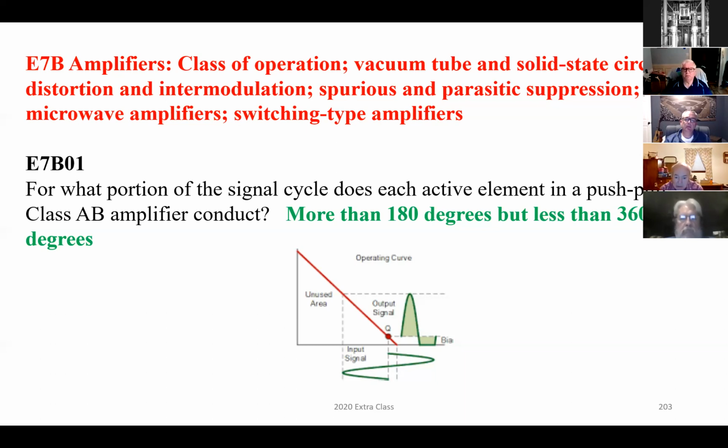It shows both. It produces a portion below the 180, doesn't it? Down on the other side, the bottom curve. No, because you've got a small amount that the circuit doesn't bias, so it's not going to conduct until it's biased. So that's what they call crossover distortion, because it's not going to be fully biased the whole time. A class A amplifier is fully biased the entire time, but it also is very inefficient, and you lose a lot of energy to heat with a class A.